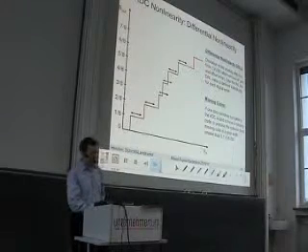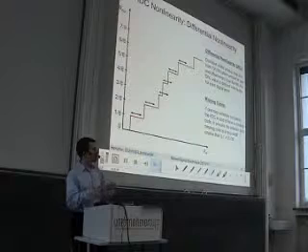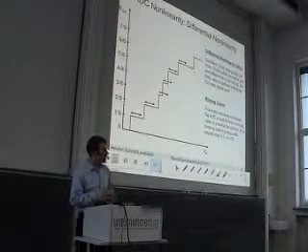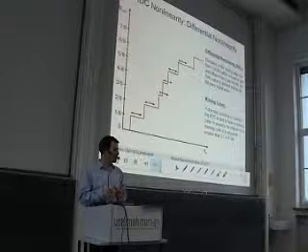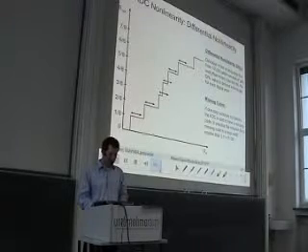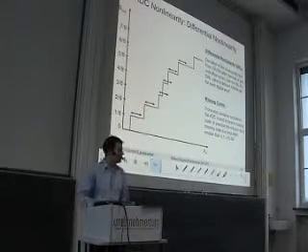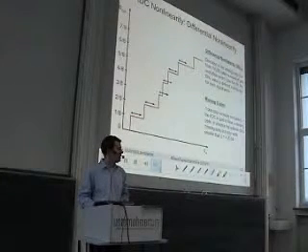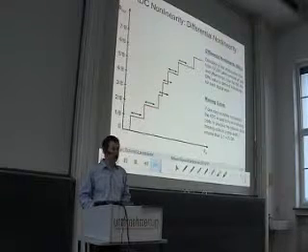Again, there is a definition of a differential nonlinearity, and the differential nonlinearity is again a local quantity, whereas the integral one is a more global measure for nonlinearity. And the differential nonlinearity, exactly the same definition, is the deviation of the actual analog step size from the ideal one.